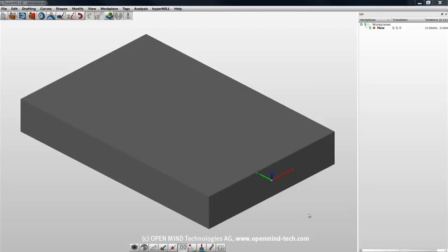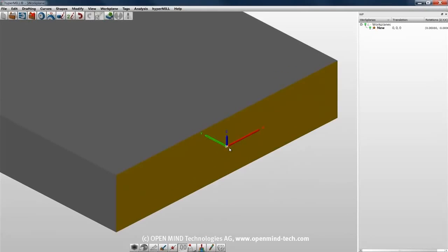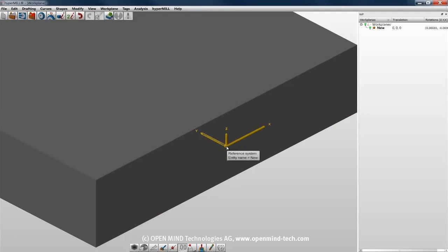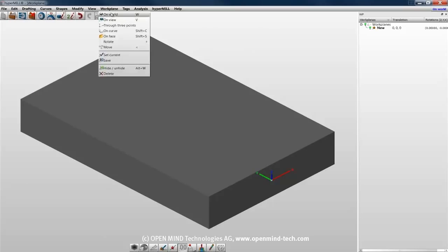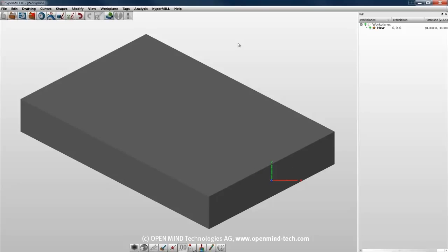The workplane is displayed in the graphics window as shown here, with a small sphere representing the origin and bold red, green, and blue pointers representing the X, Y, and Z axes. By default, the workplane is located at the system origin or world coordinate system. The onWorld command will snap the workplane to this location. The onView command will set the Z axis to the current viewing direction, keeping the origin in its current location.